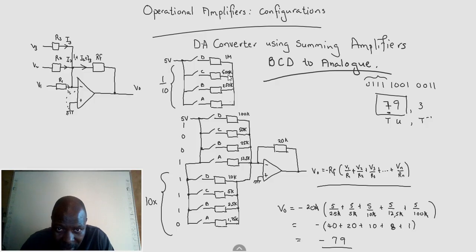And again, this is 2 times less than that. And then lastly, it's going to be 125. So we can obviously go higher. If you want to have 100 Hz, we're going to divide by 10 there. The currents, the resistors are going to be 10 times bigger. And if you are going to want hundreds here, you are going to increase the currents by a factor of 10, and then that means the resistors are going to go even smaller, all right?